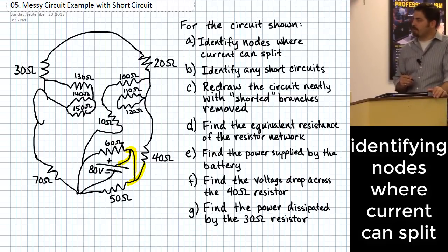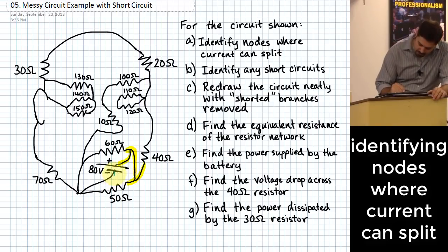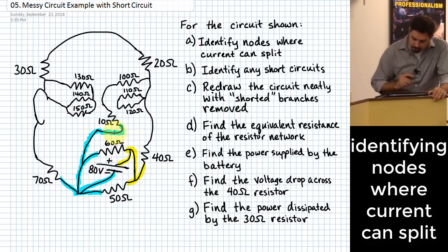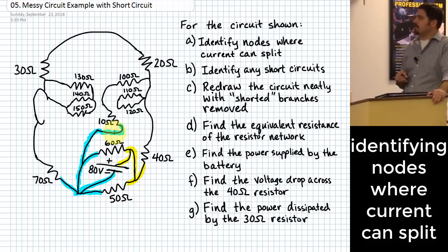Okay, how about the other side of the battery, right? I can start highlighting this stuff, and I go as far as I can go to the point where I run into circuit elements. So I run along here, and I take my furthest extent until I run into a circuit element. Okay, so all that stuff that I just highlighted in blue, that's another node of this circuit.